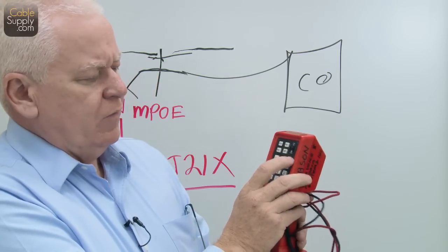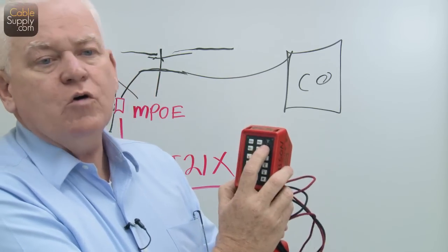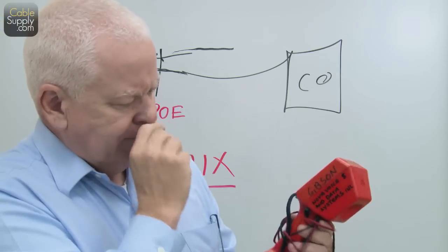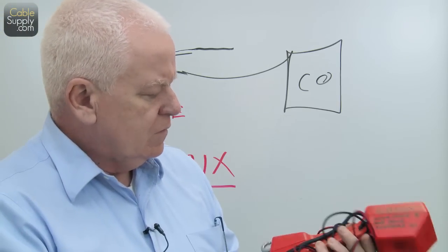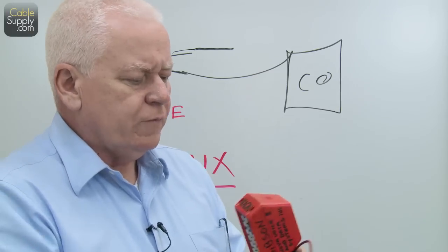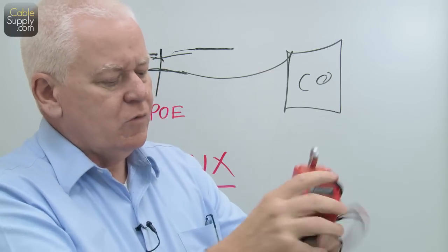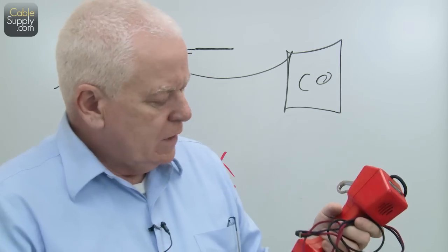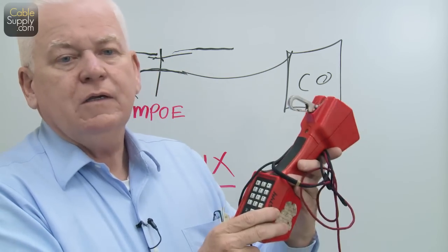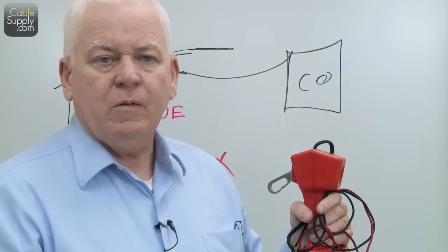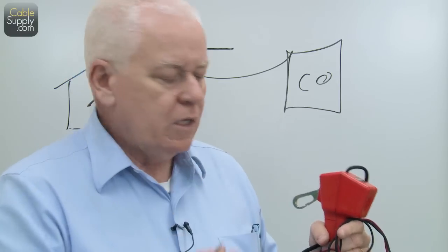This is your DTMF. So you have pulse or tone setting on here. Most people keep it on tone. I don't know what else to tell you. You can listen, you can talk. It's a wonderful device. It's also a speakerphone, which is really nice because if you hang it up in the phone room and you connect it and you're looking for a line, you can hit your speed dial and just listen and write down the phone number as the phone company reads back to you what line you're connected to.